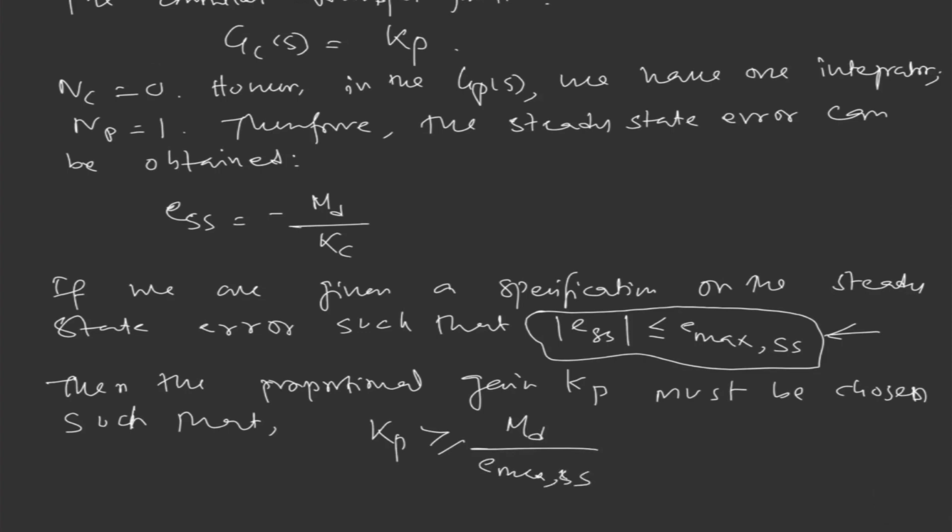This is how we can come up with the condition on how Kp, the controller gain, should be chosen so that it can fulfill the objective on steady state error. This is very, very important. How can we achieve your mission objective? If you want to maintain a desired attitude or position of the aircraft, and some steady state error in the final stage, what conditions do we have to follow? This is how we can improve the performance of the controller.